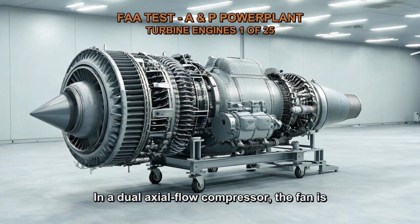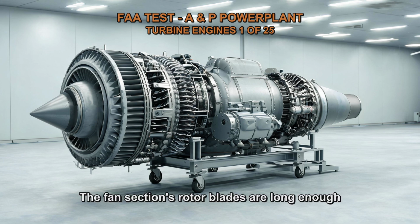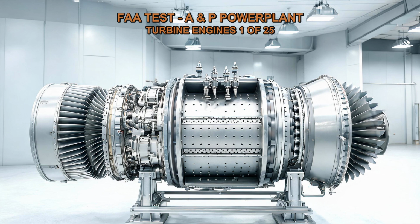In a dual axial flow compressor, the fan is a component of the low-pressure compressor. The fan section's rotor blades are long enough to allow the air they move to circulate around the engine's gas generator. The low-pressure compressor rotates at the same speed as the fan.